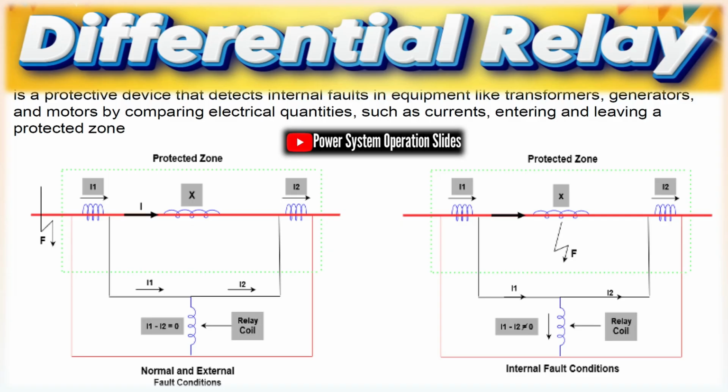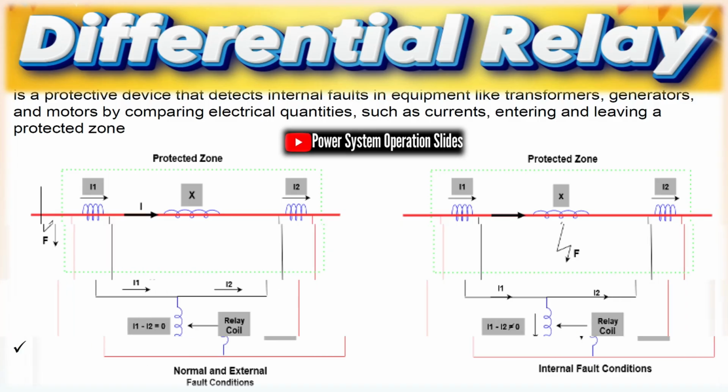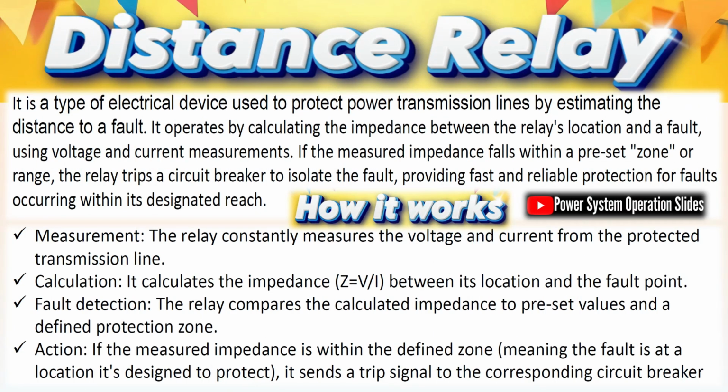Lightning arrestor rod/mast. A lightning mast intercepts direct lightning strikes and diverts current safely to ground. It protects structures by providing a preferred strike point. It covers an area with a defined protective zone.